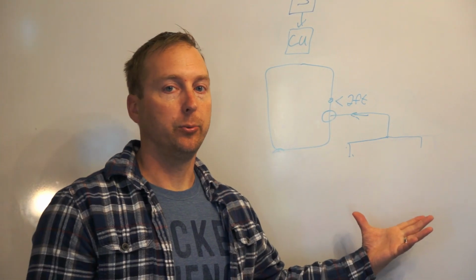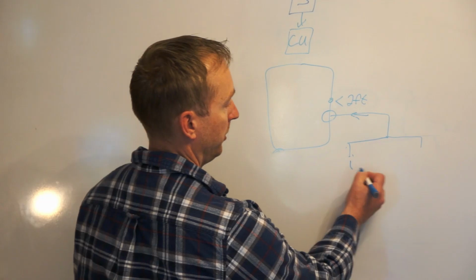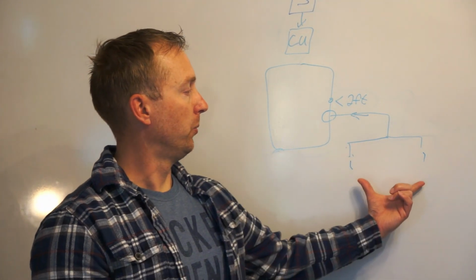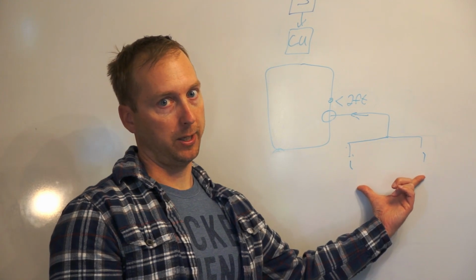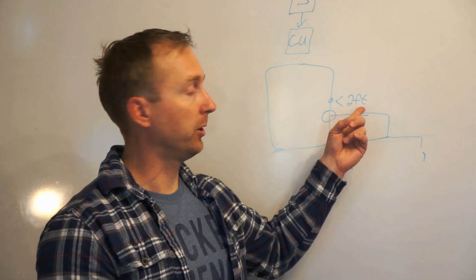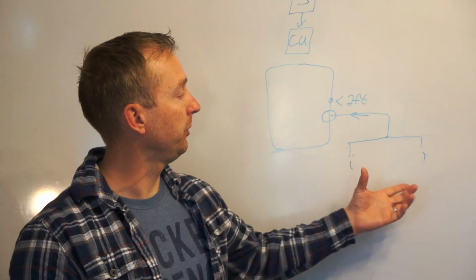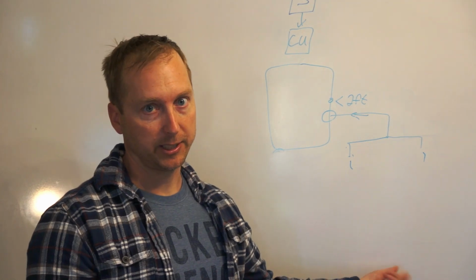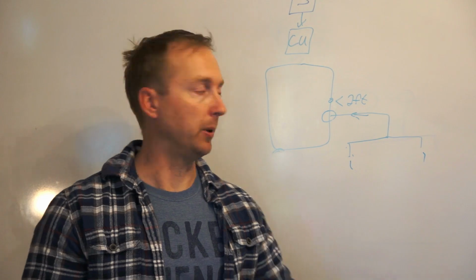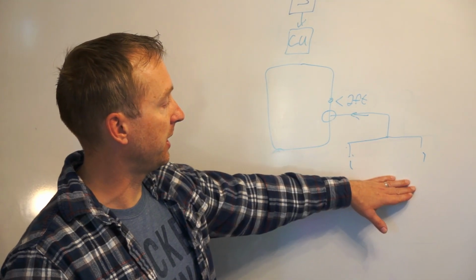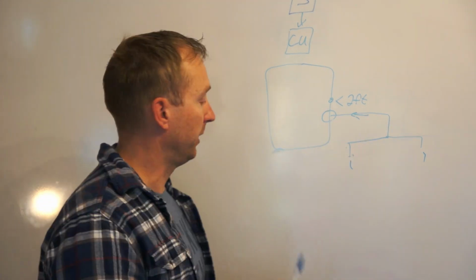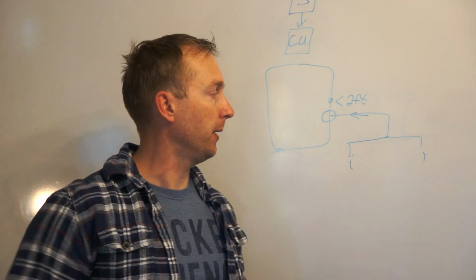So let's start off with if they're the same. So we have 1 and 1, but it's still less than 2. We can ask our robot to just shut off. So say, hey, they're the same, but we can't go back into this loop because we're still under 2 feet. Then we'll just shut it off, set off an alarm, and we as an operator will go and reset the robot. Or we can just say, choose a side, back up, turn right, and then repeat the process. If we're in a corner, it's eventually going to work its way out.